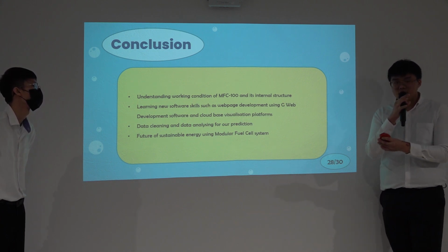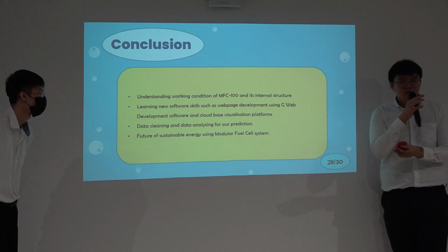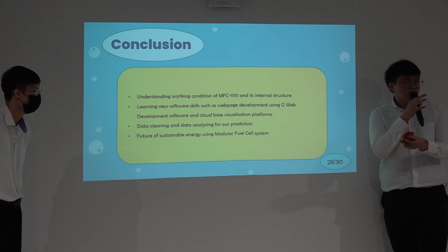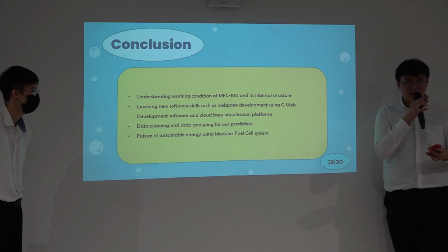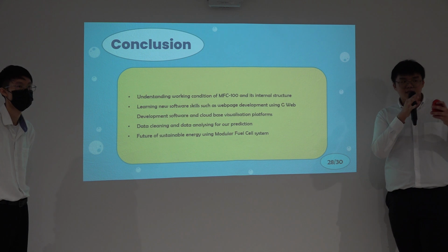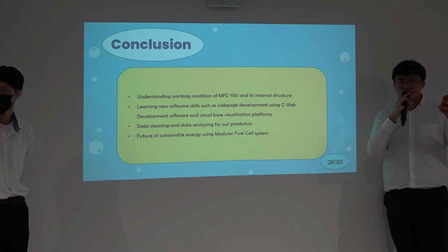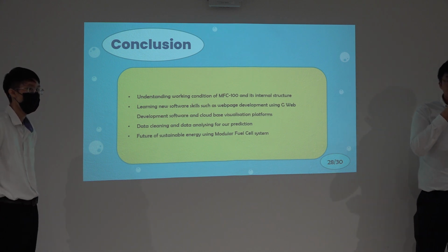On average, a fuel cell will produce about 0.6 volts to 0.8 volts. So if, let's say, you want to power up a DC device that is 8 volts, you will need 10 fuel cells put together, and that is when you call it a fuel cell stack. The fuel cell stack has scalability, in which you can increase the number of fuel cells to produce a higher output voltage, or you can have fewer fuel cells put together to produce a lower output voltage.